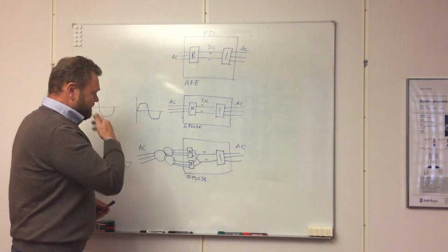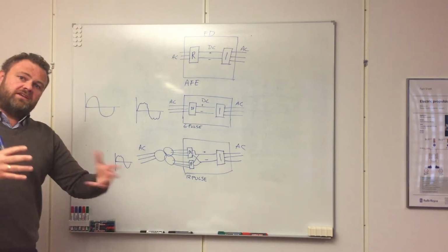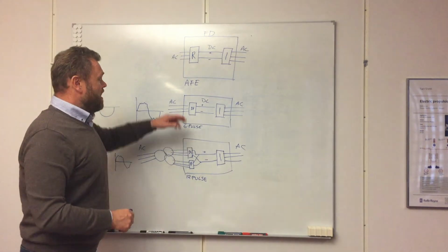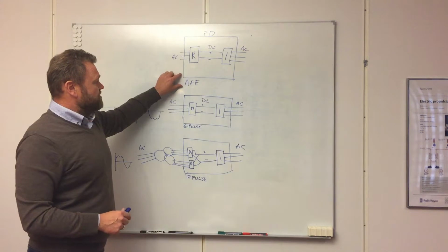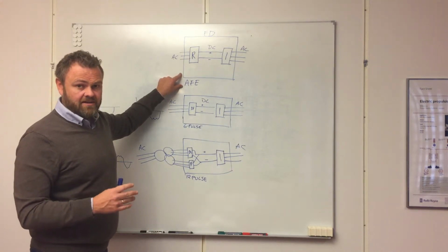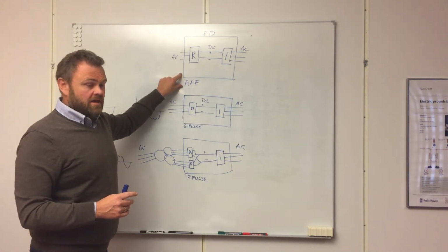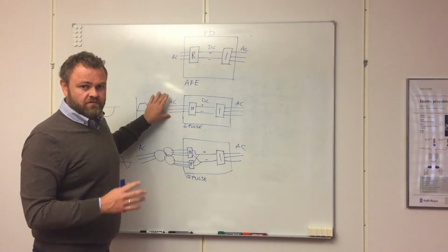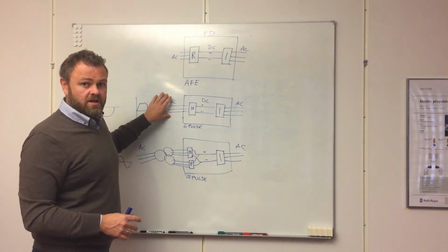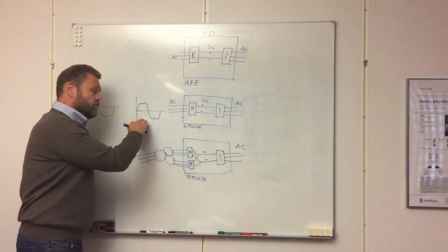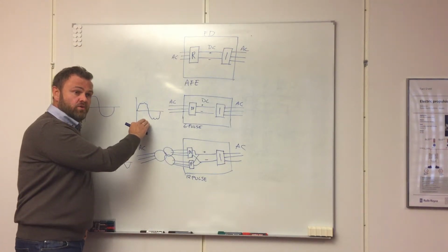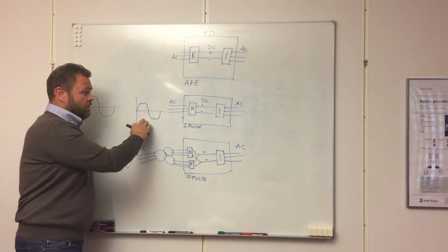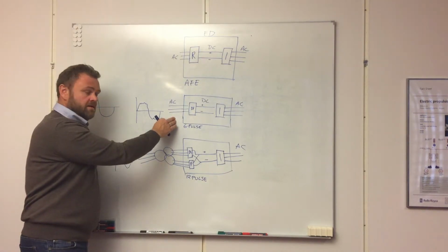So the first thing you see is, why do we in Rolls-Royce normally use an active front end? Well, we will not use a 6 pulse for a big propeller load, because we would destroy the voltage on board the vessel. So we wouldn't do that.